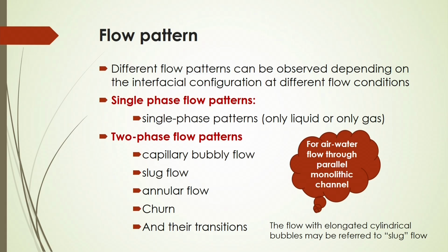Two phase flow patterns include capillary bubble, slug flow of the liquid, and even annular flow. That means in the core region there will be one phase, and in the wall region there will be another liquid. So, that is the annular flow.